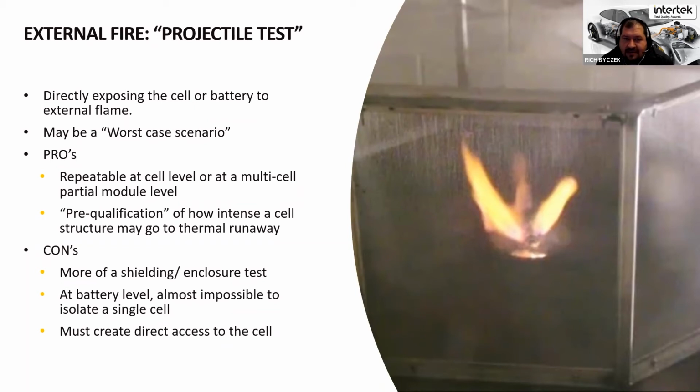We also have the case where, depending on how you apply that fire, you may or may not be hitting that worst case position on the battery. From a regulator standpoint, that worst case is going to occur in the field. So you need to be sure that you're trying to create that worst case in the test lab.